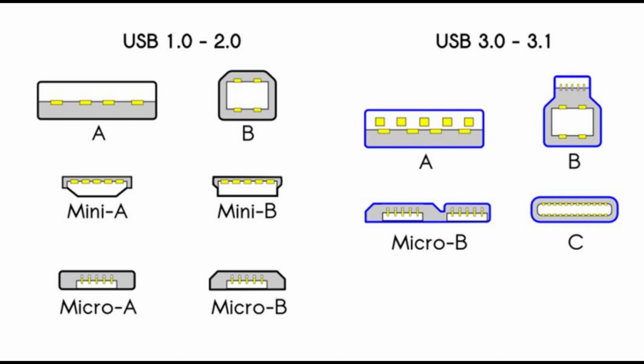The SuperSpeed architecture provides for an operation mode at a rate of 5.0 Gbps, in addition to the three existing operation modes. Its efficiency is dependent on a number of factors including physical symbol encoding and link level overhead. At a 5 Gbps signaling rate with 8B/10B encoding, each byte needs 10 bits to transmit, so the raw throughput is 500 MB/s. When flow control, packet framing and protocol overhead are considered, it is realistic for about 2/3 of the raw throughput, or 330 MB/s, to transmit to an application.